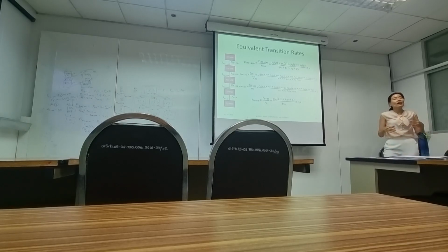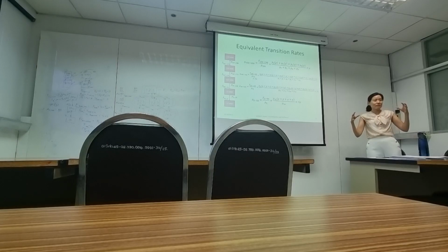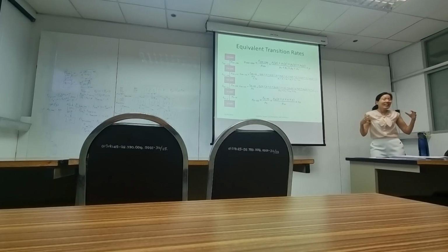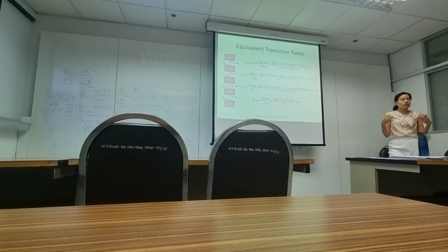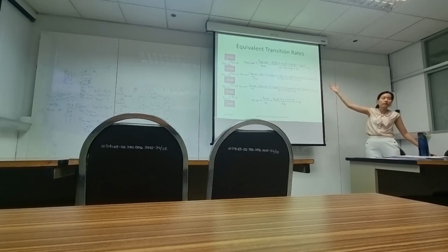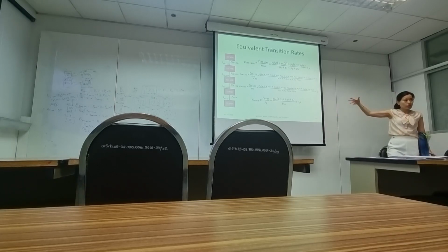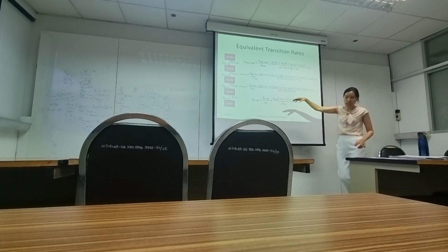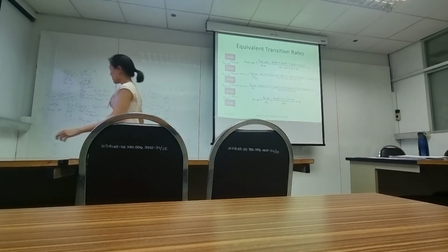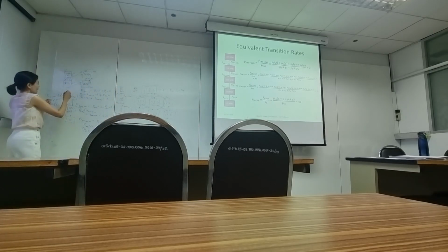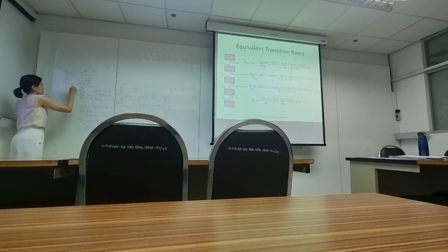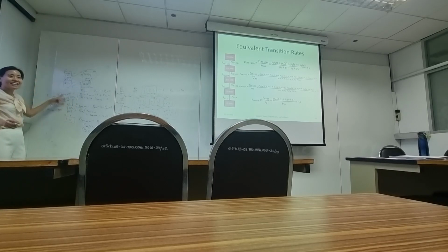So that we don't need to write out the whole state transition diagram every time we have 1 more unit adding into the service. The unit addition algorithm is useful when you have an existing equivalent model like this and you want to add 1 more unit in your network, and you don't want to recalculate all these tables that you already have.